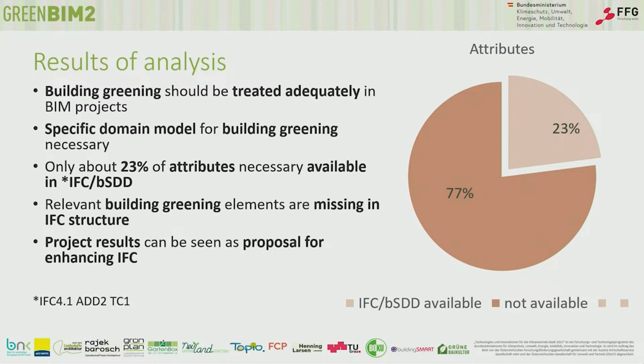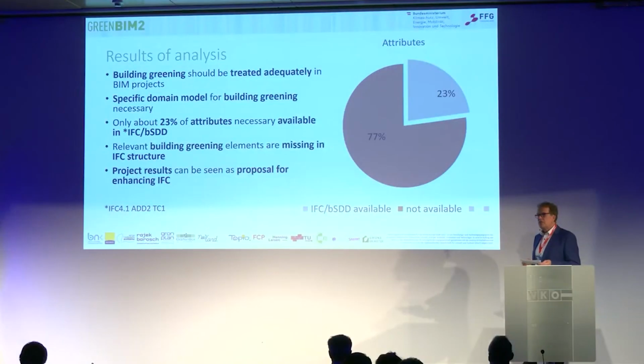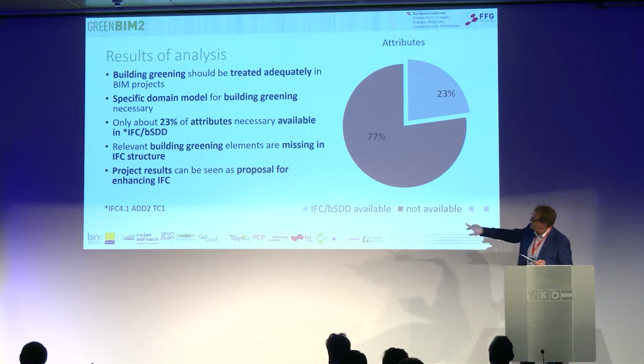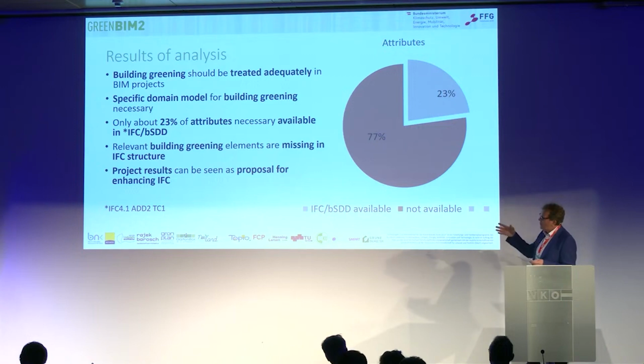Relevant elements for building greening are generally missing in the IFC structure, and for specialists, this analysis is built on the older IFC standard 4.1 here.